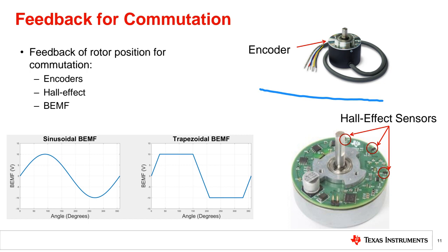However, in pump and fan applications, we do not need very sensitive speed control, so you can use a Hall sensor. In servo applications, robot arm applications, or for example home service robot applications, you cannot use a Hall sensor. You need to use an encoder.